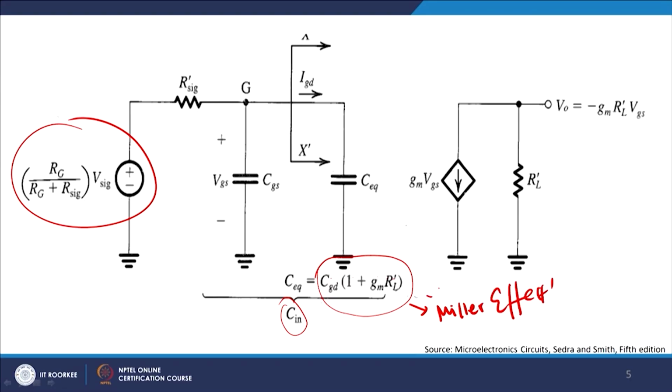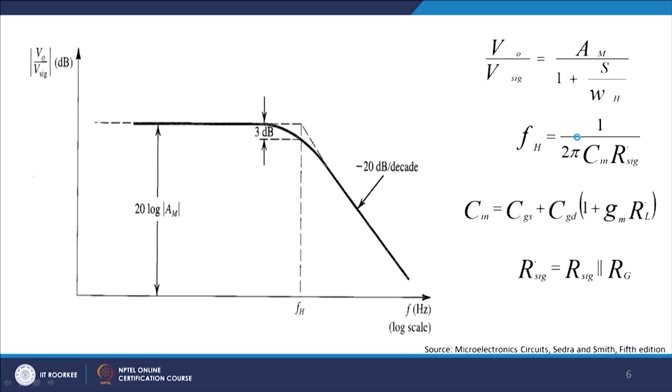This is known as Miller effect, right, and therefore I get the overall voltage will be gm RD. So, gm RD is nothing but gm times RL into VGS. Why? Because gm is del ID del VGS. So, this VGS cancels with this VGS, ID into RL will give you the output voltage V0, right, and from here you can get the value of output voltage in a much easier manner, right. If we now come to the low frequency domain of this device, maybe we can explain to you.